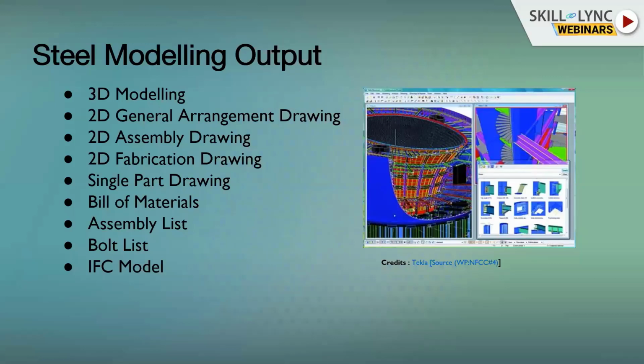IFC model is a very important thing, because with the IFC model we can export our model as per our global coordinate system or our local coordinate system. In TEKLA, they have introduced their coordinate systems here, and we can easily set base points here, and we can export our model from global coordinates. So any other disciplines, maybe they are using some other software, they are not using TEKLA, so we can export our model in global coordinates and then we just send it to them so they can import the model and check those things.